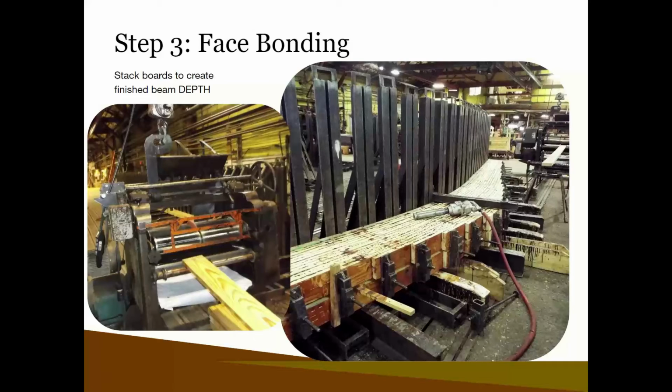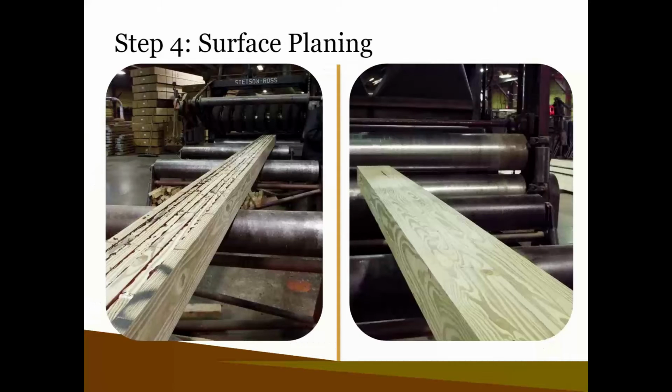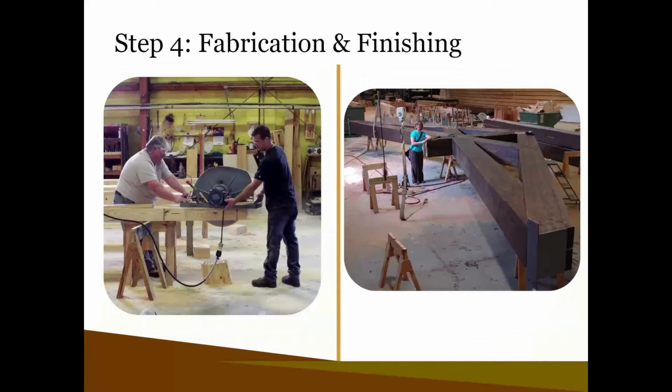And you can see there's uneven plies, there's glue squeezed out. So the next step is to send it through the surface planer. This is where we get our different dimensions from the rest of the lumber and timber industry when it comes to custom manufacturing, because we're smoothing out all of those edges, cleaning up the glue, so you get a nice exposed face. Next step, okay.